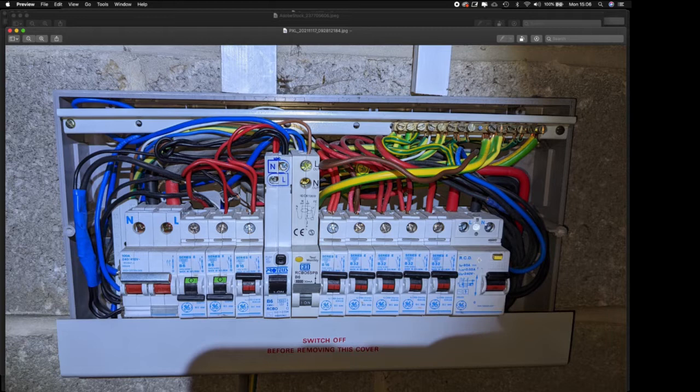So if you've got metal light switches, sockets, if you've got metal casing on your oven, anything like that, if there's any current flowing to earth, which shouldn't be, not anything over 30 milliamps, which is, you know, very small amount of current, then the RCD will operate. So if there's any current flowing to earth, i.e. through the human to the floor, it'll trip very quickly.